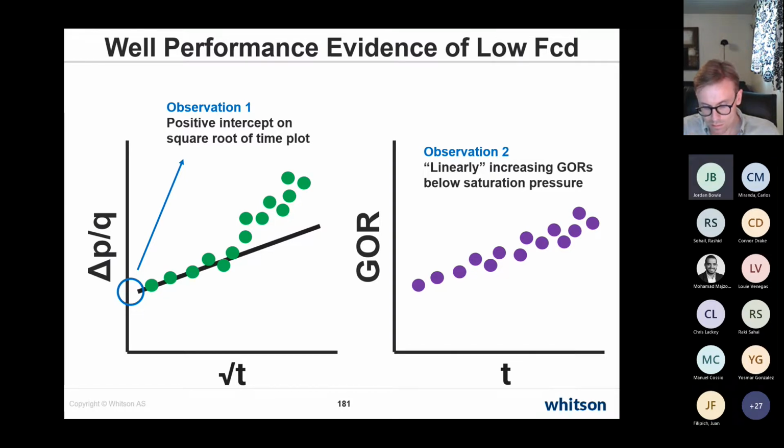There's not a lot of volume. So looking at the pressure profile on the numerical models, if the model is taking a lot longer for the pressure to build up when the well is shut in than the actual well did, that could be a sign to drop down your conductivity.